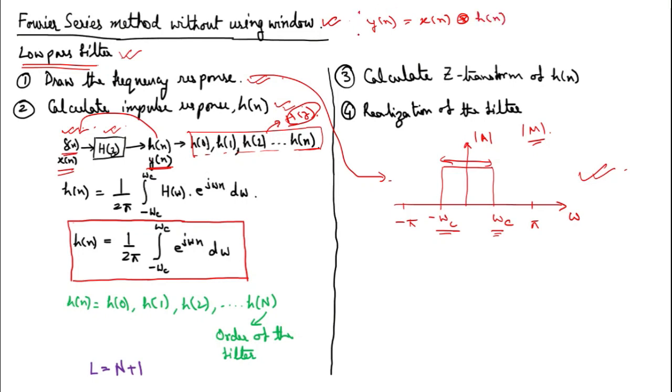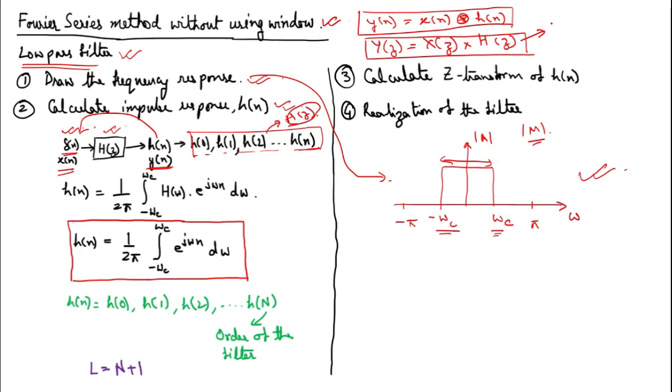Okay, so this convolution is in the time domain, and in the frequency domain, we discussed that Y(z) is equal to X(z) multiplied by H(z). What is H(z)? H(z) is nothing but the transfer function of the system, right?